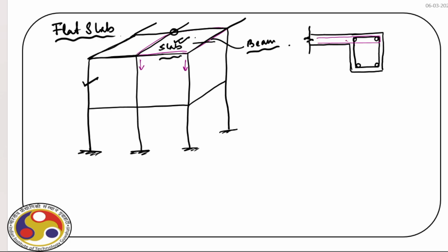And then we have slab reinforcement in other directions. Now, depending upon the location, we can have this top reinforcement or not. If it is at the corner, you have seen that we have some additional reinforcement. Now, at least this reinforcement at the bottom will be there.